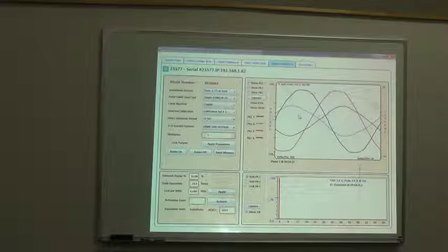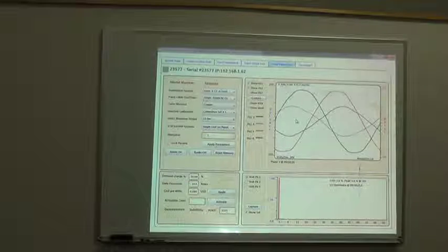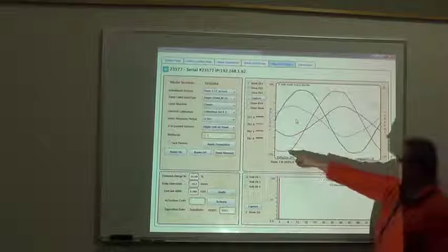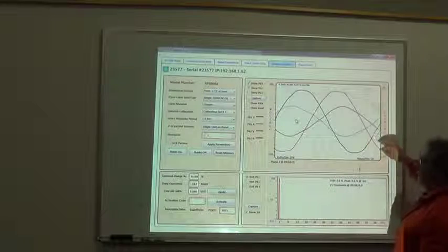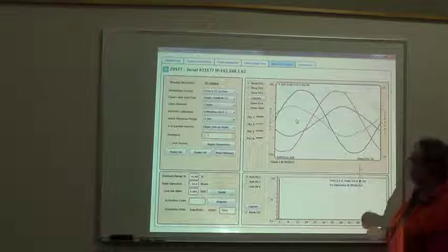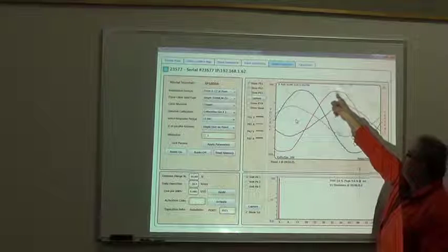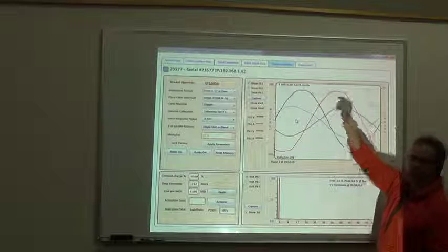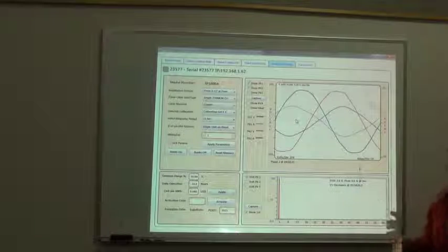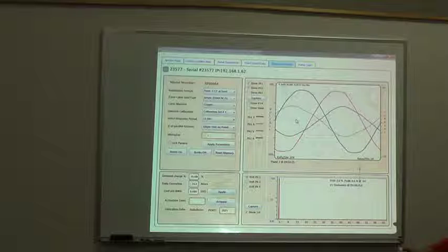Connie, so this is what I was talking about the line code. This is the reason why I had a bad connection. This is the voltage for phase 2. This is the current for phase 2. You can see on the diagram on the left, the center point of this is a little bit after the red one. That's what you'd like to see. That means there's a power factor, right?